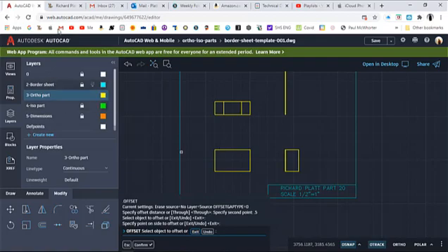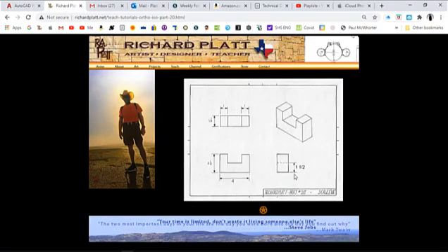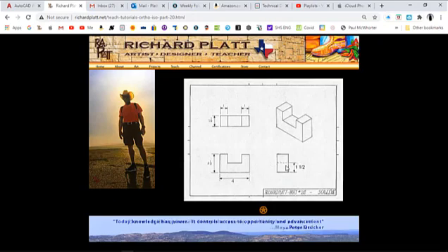Now let's go back and check our drawing again. And now we've got, it says 1.5 inches. Now we know how to do this. Okay, that's going to be 0.75. So we're going to draw a line 0.75, then I'm going to change it to a hidden line because we don't see that line. And then we're going to use that plus this up here as a basis for drawing these extension lines into getting the front of a part taken care of.